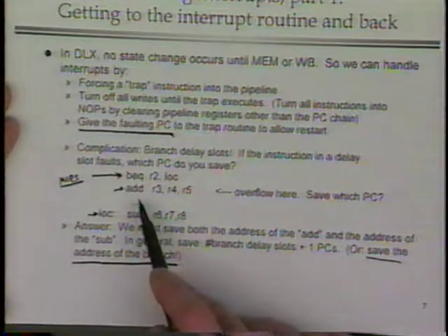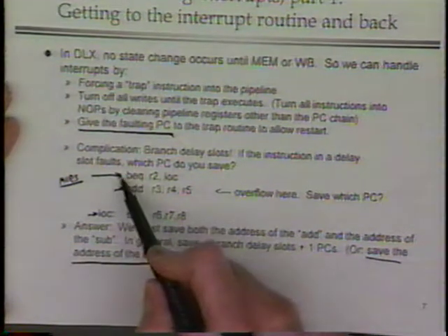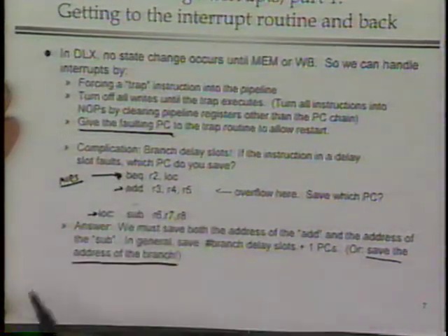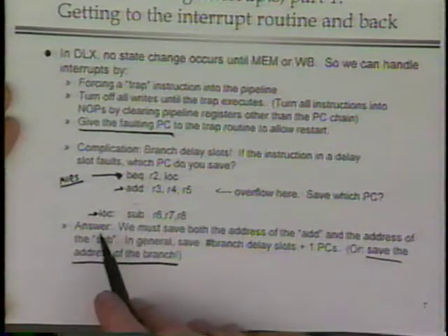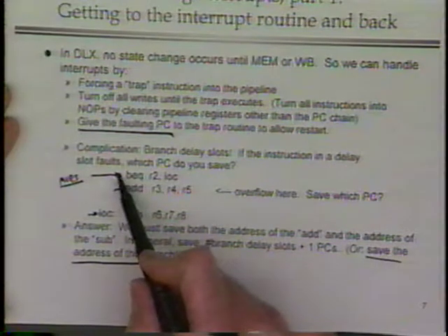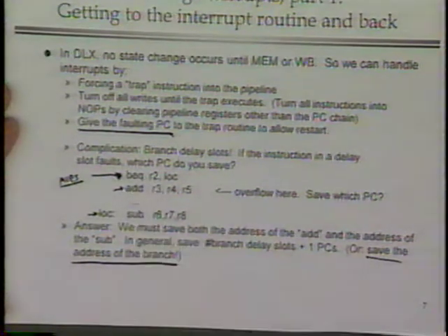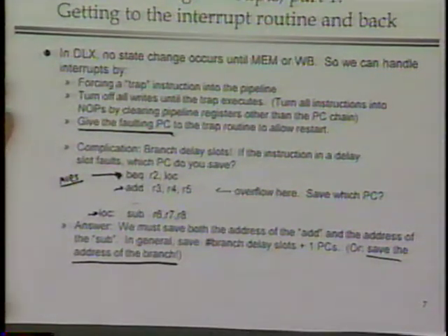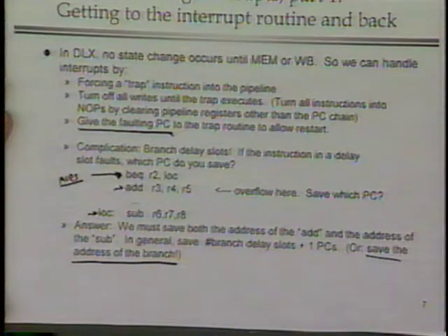One of the things you've got to be a little careful about there is to let the software know, or give it enough information to discover, exactly which instruction was faulting, because now it's pointing at the instruction before the one that actually caused the error. And if it's trying to do processing based on what the error is, it obviously needs to know what the appropriate thing is.